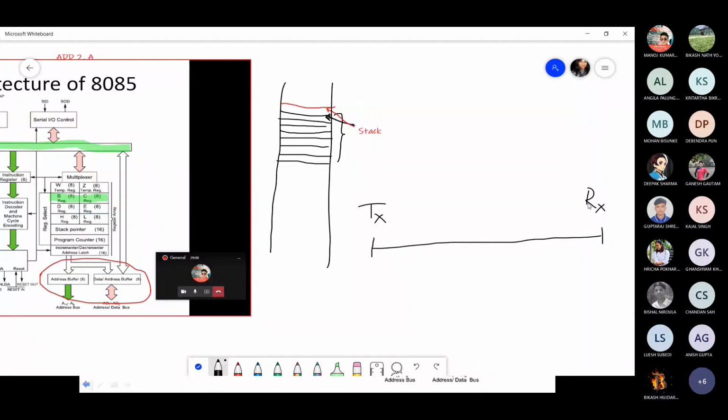There will be attenuation in any transmission line, but a TTL compatible logic requires that a logic 1 will be decoded as if it is 5 volt. If it is 5 volt, then it will be logic 1, and if it is 0 volts, then it will be logic 0. So that is TTL logic. But what we have is that the voltage is decreasing due to the attenuation process. So what we need is an amplifier. In any transmission line, what we need is an amplifier, number 1. And we also might need to store the data for a certain time.